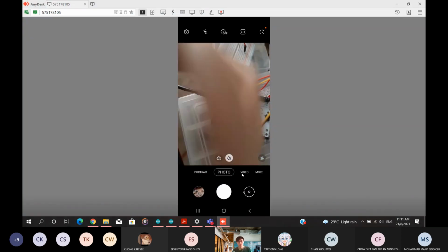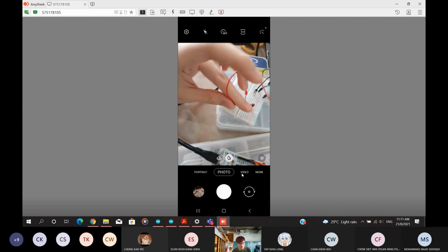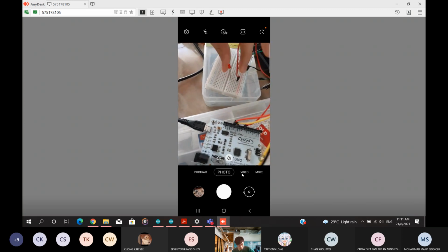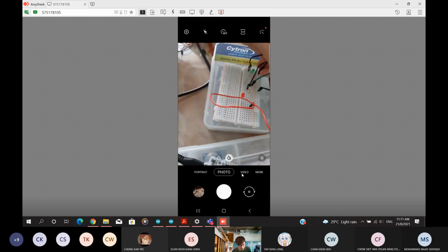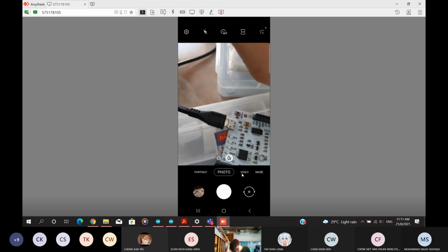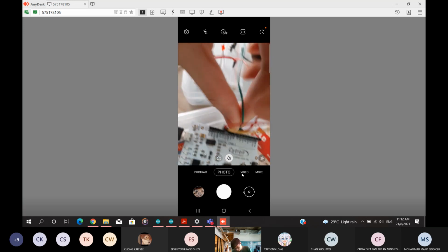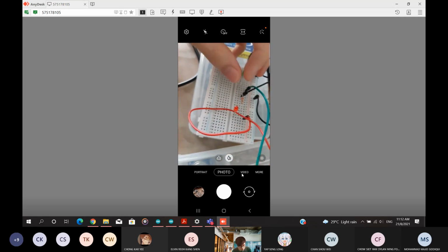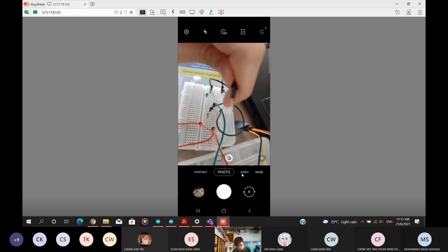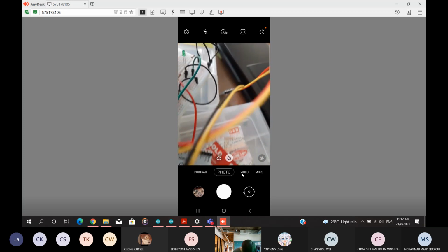Yeah, now you guys can see. Pin number 8 is over here, and my red LED is connected to this. Right? And then afterwards, my green LED is connected to number 9. Right, my green is here to number 9. Okay, and this one will be connected to ground. I just need to borrow any ground over here in the Arduino.